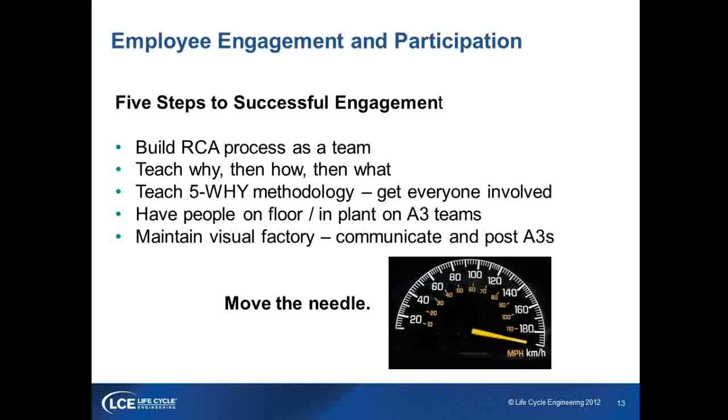To get people involved, I always like to use a 5 why methodology that allows people on the plant floor, in the field, whether it be operators, mechanics, people at that front line, to get involved. Where if I have a pump failure, my operator doesn't press the call button and then go sit in the break room. He's out there with the mechanic, with the electrician, troubleshooting, right? And so the expectation on site needs to be from supervisors on down that everyone has ownership in the equipment, in the problem-solving methodology, and I found that a 5 why methodology is a great way to instill that with your team.